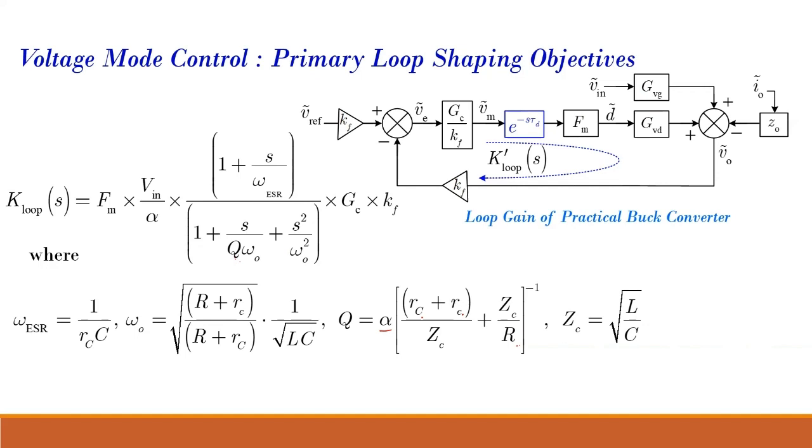That is how well designed the inductor is. But in this case, the quality factor is for a second order system. When you analyze the second order, it is 1/2 zeta. So if the damping is less in the circuit, then your quality factor is more. Just assume there is an R, L, C. If your R tends to 0, what will happen?